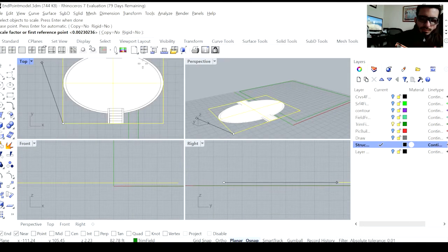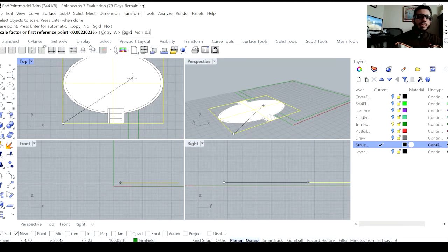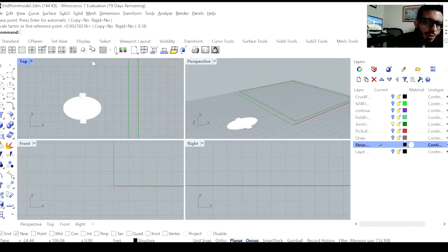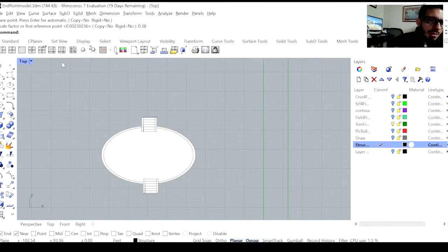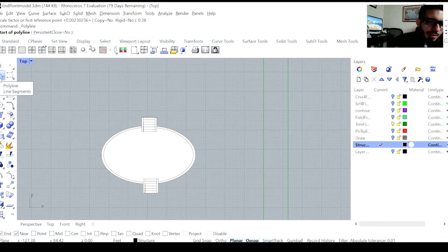So now I'll bring the 0.388. There you go. I didn't have to choose both points, because when you choose both points, you then use the mouse to scale, which is not very precise. So what you need to do is just choose one point and scale it down. Now this should be around 50 feet, and we can double check. It doesn't have to be exact in my case. I just want it to be a little closer to 50 feet.